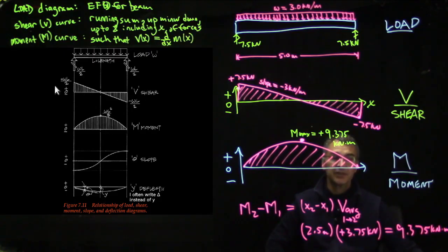By the way, this shear diagram is the integral of minus the distributed load. If you look at this w of x, this shear diagram is actually the integral of minus w of x. That's because the distributed load points down. If you put a uniform load on a beam, it's a load pointing downwards. So that's why a positive value of w of x gives you a negative value of the shear diagram, because w of x is a downward load. Okay, below the shear diagram, you draw the moment diagram, which tells you the magnitude of the moment at position x, saying how big the torque is. If you cut the beam in half at x, how big a torque would one half have to exert on the other half cut at that value of x to keep everything in equilibrium.